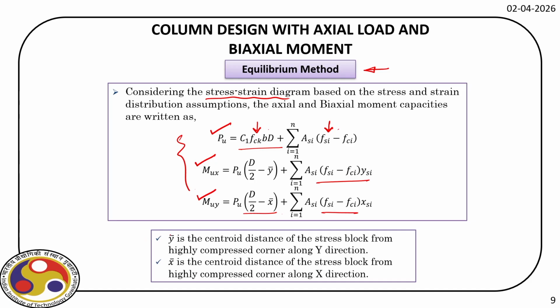Out of that, this y bar here and x bar here represent the centroidal distance of the stress block from the highly compressed corner along y direction and along x direction, right? So we'll see that block diagram in a minute.